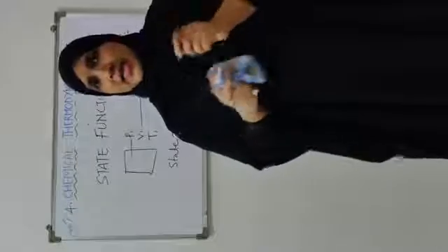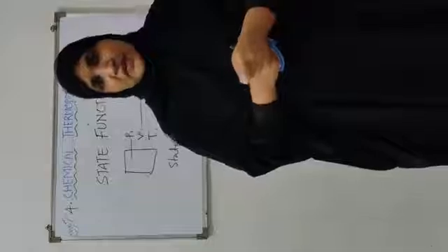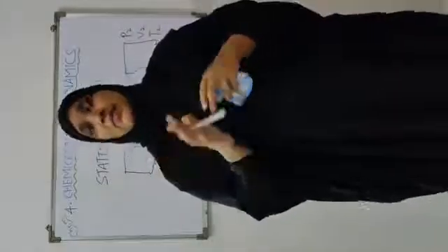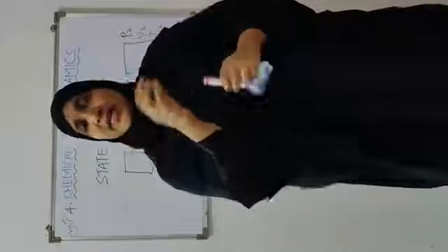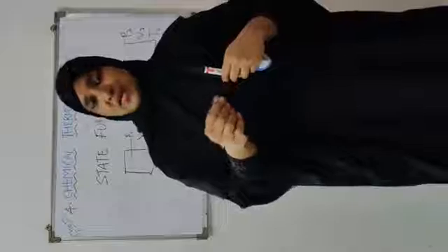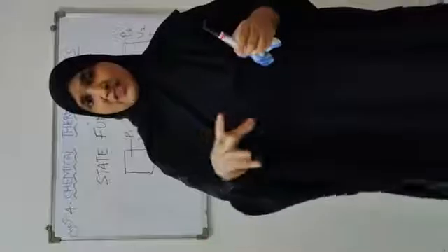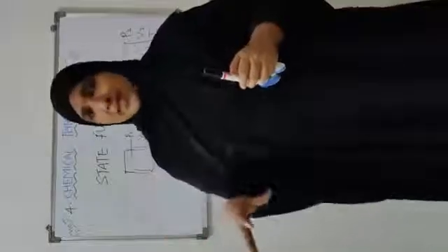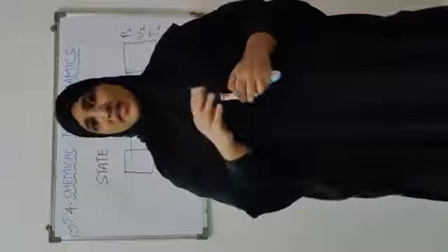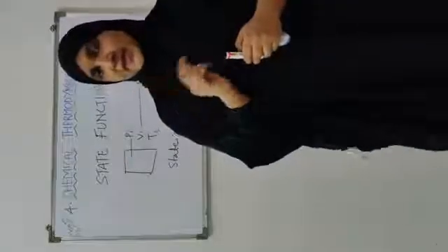Okay. Another kind of functions are also there which are known as path functions. What are path functions? These are not properties actually, the quantities of the system that depend on the path followed to reach the particular state are known as path functions. Path functions depend upon the path and do not depend on the current state. For example, work. Work is a path function.